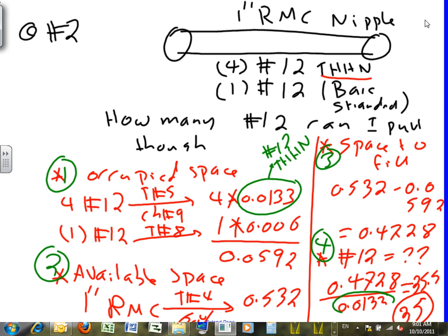If you go to the 3rd column, do you see where it says quantity? Count 1, 2, 3. Do you see the word quantity at the top? If the quantity is 1, that's solid. If it's 7, it's stranded. Stranded is basically other than 1. So for number 12, it's not the first number 12, it's the second because it's stranded. Go across all the way, and you'll find the cross-sectional area is 0.006, not 0.005.